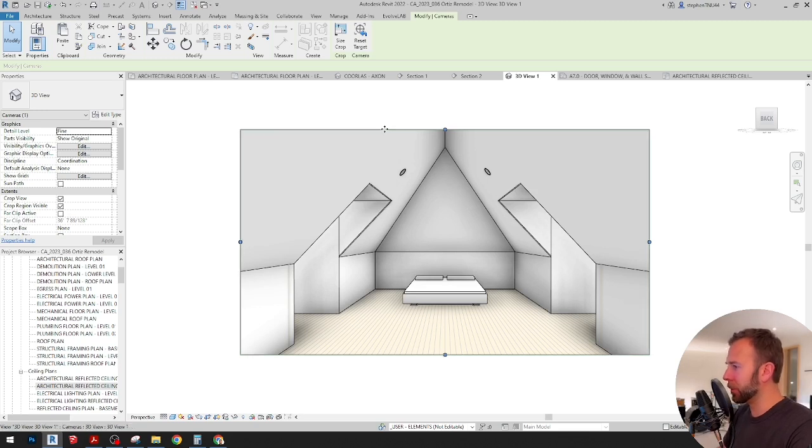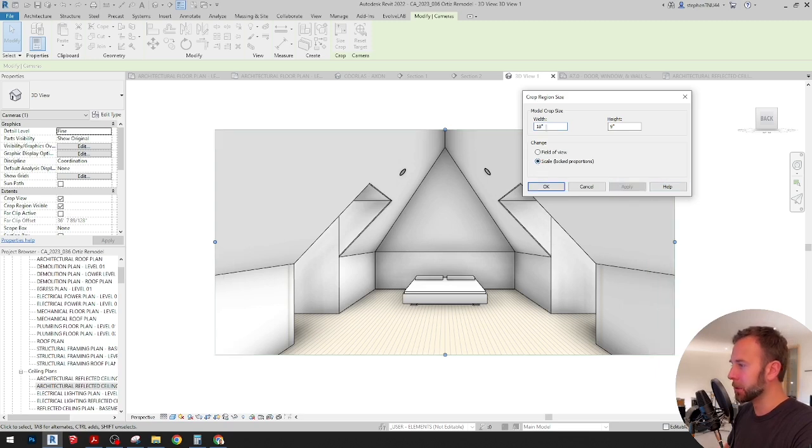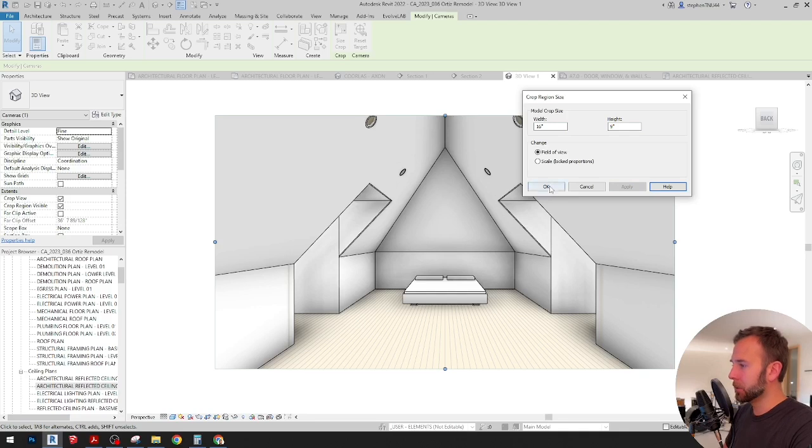That's okay. I think I want to get a little more distance away, capture a little more, and then maybe even open up the camera a little bit. So it looked like it was just under 90 degrees. I think if I add a couple more inches to each side, it would open it up to about 90 degrees. So I'm going to do 18, field of view, apply, click the scale, kick it back to 16, and then click on the field of view again and make sure it's 16 by 9. So that's a little better.